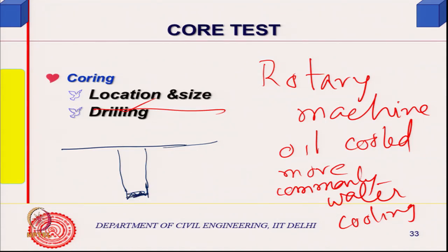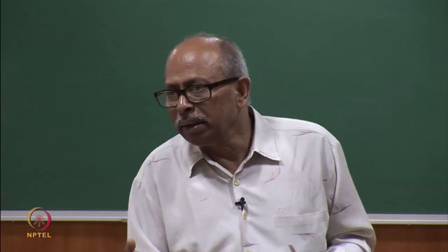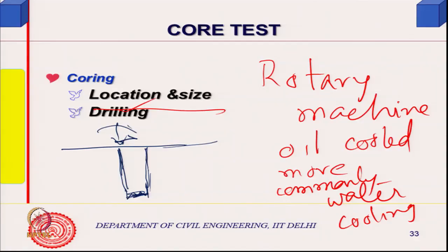Then what you do, you simply shear it off by giving some sort of pressure like this, or a moment or something of that kind. You put a wedge or even a screwdriver does the job, and just break it. When you shear it, you will have this undulated. In fact, the piece you get may not be very polished at the surface, but surely it will be somewhat undulated at the bottom. So, what you do? You trim it here and might trim it up also. This is called trimming.